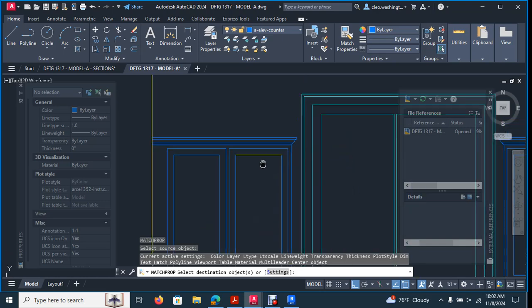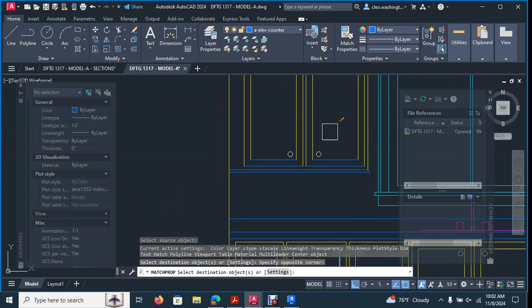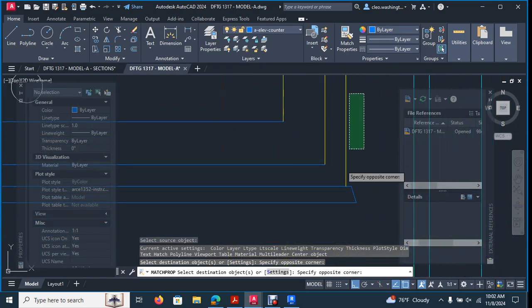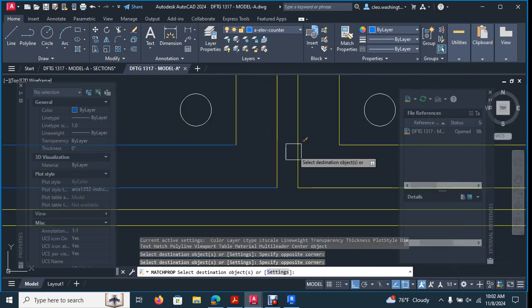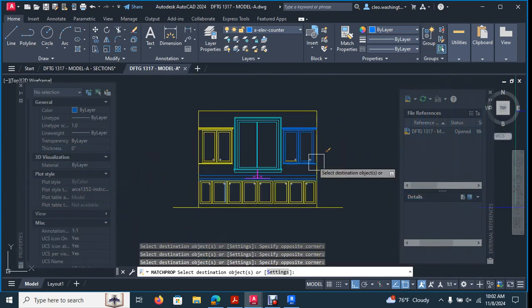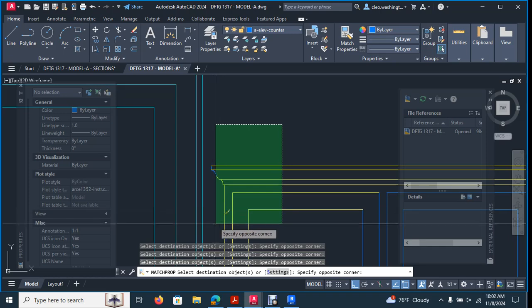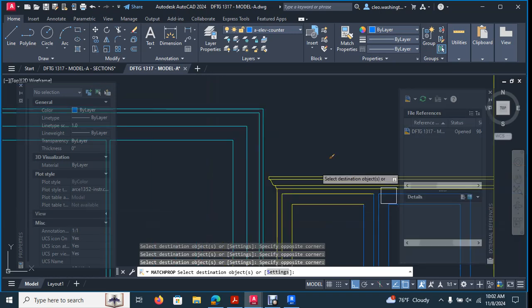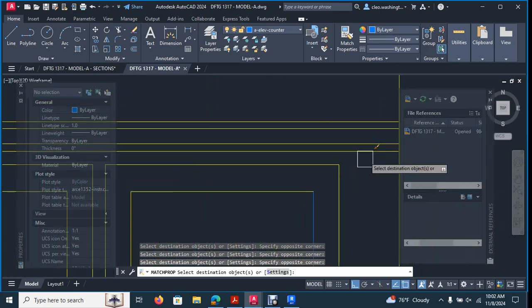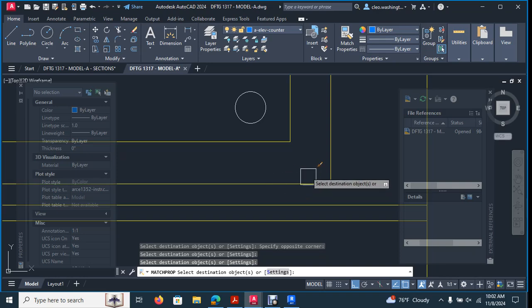We have two separate ones because I guess I didn't see that one that had been created already. But let's put these on that layer. And there's one thing we're going to have to do. We're going to put 10-foot ceiling heights in every room, okay? 10-foot ceiling heights on all your interior elevations.